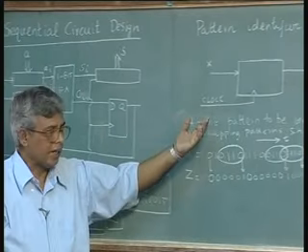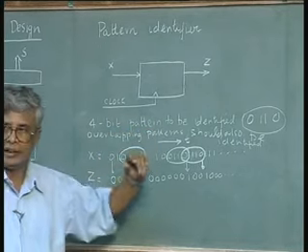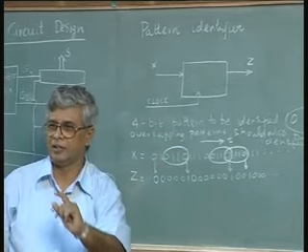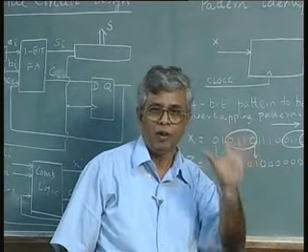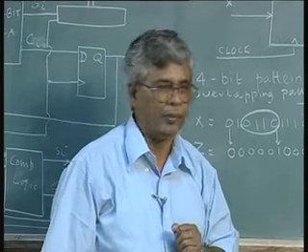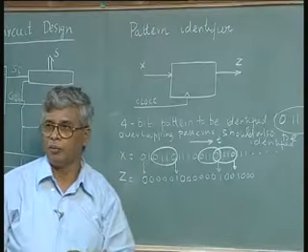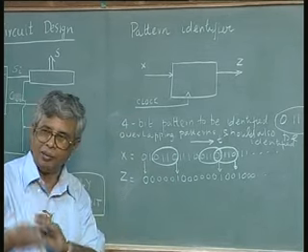Now in this case, since I am going to design the circuit, before I start with the design, one of the first questions I should ask, along with the patterns and overlapping etc., all the specifications, one more question I should ask the designer, the person who gives me the problem, is do you want it as a Mealy circuit or a Moore circuit? So let us say make it simple again. As I said, Mealy is slightly simpler than Moore.